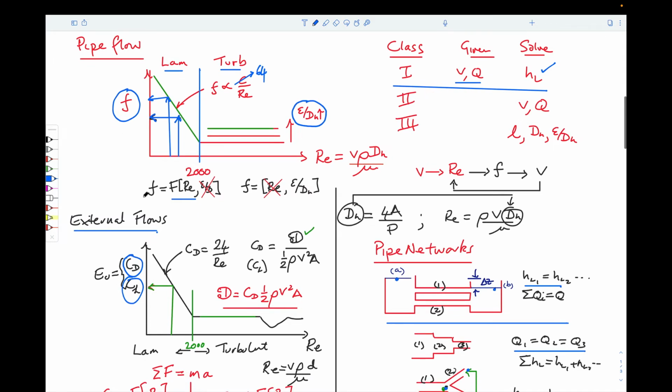But the friction factor curves look the same. They have this laminar portion and a turbulent portion. The laminar portion is a function of Reynolds number, and depending on the shape of the structure, this has a number attached to it. And in the turbulent regime, it's a bit more complicated, in that they're not flat for all of them, but they sometimes have some undulations. But essentially, for a given structure, a sphere or a cylinder, these are constant with Reynolds number, shown by the fact that these curves are horizontal.